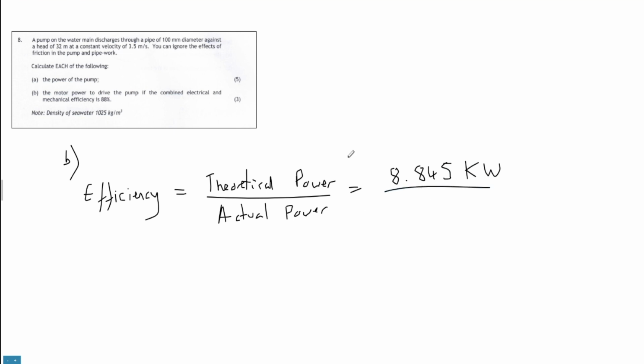The actual power is the one I'm trying to calculate. The motor drive the pump is combined. Yeah, the actual power is this one. And it's going to be 88%. So I guess I could just write it as being 0.88.